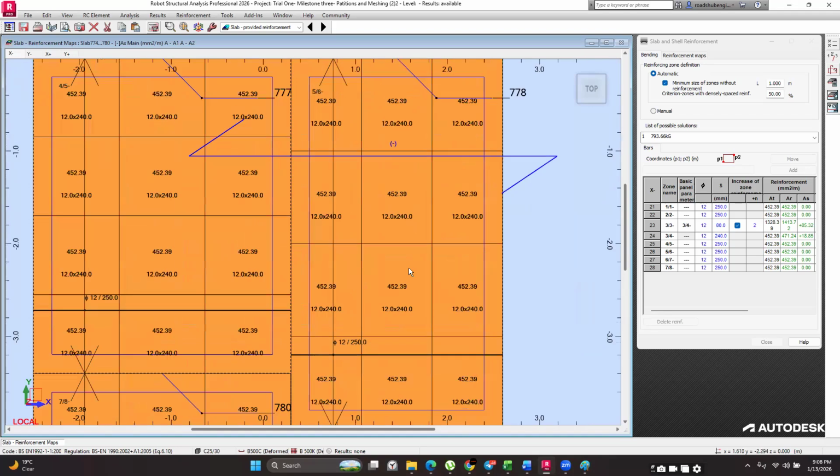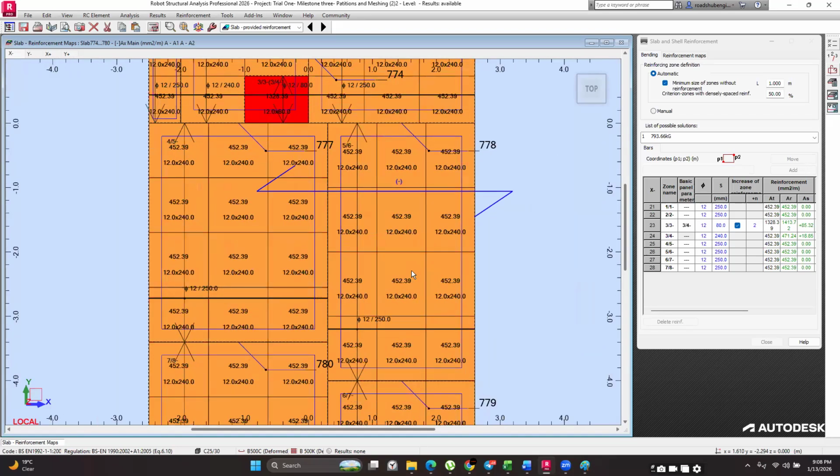Then the other thing that you may do, if it's an entire slab that you are finding the spacing is very small. The software has done the design, it has assigned the rebar, and it is finding that for particular panels, it requires a spacing of say 75, 100. It means that it is controlling things like deflection and cracking using reinforcement.